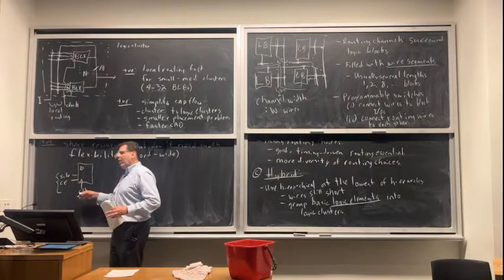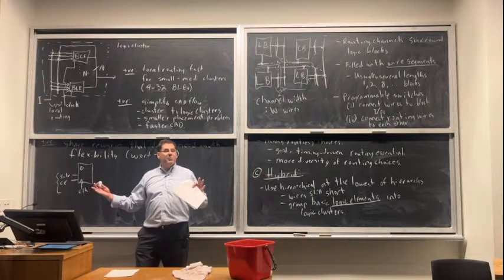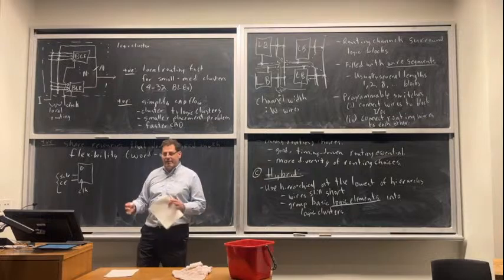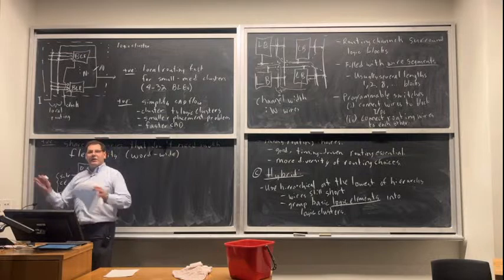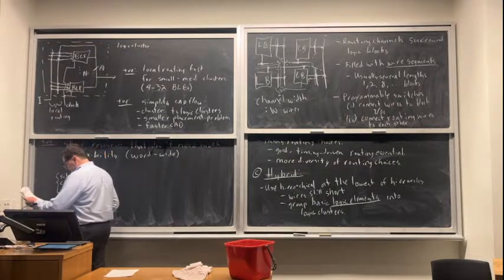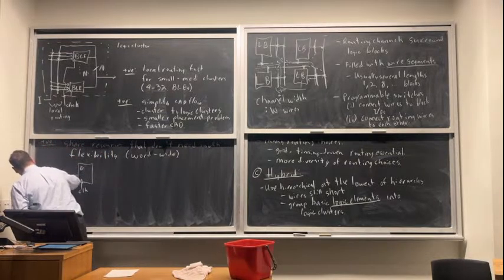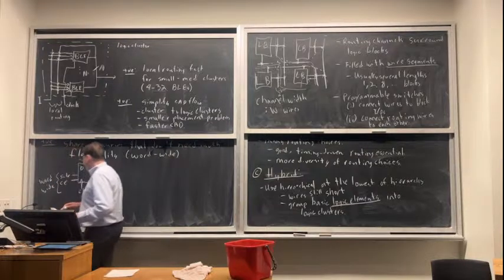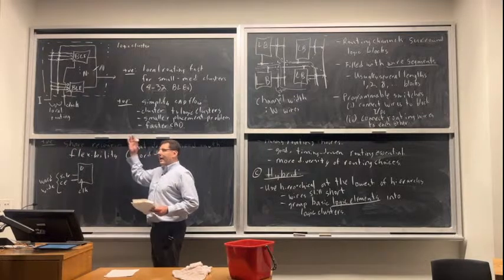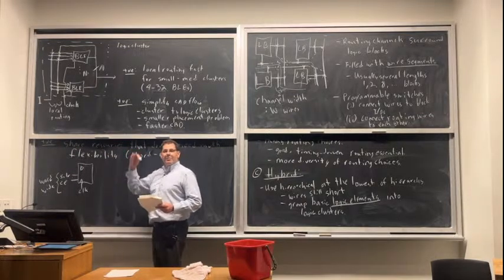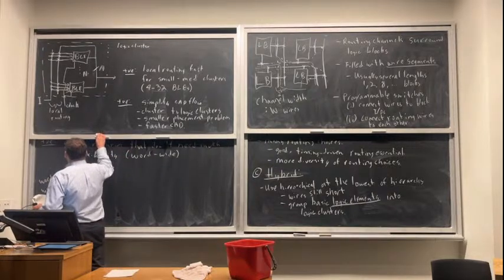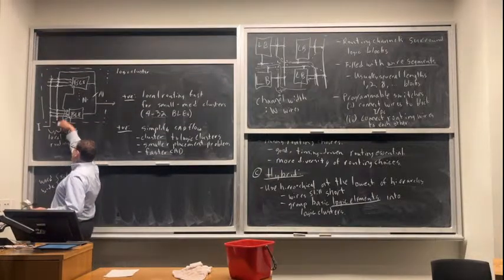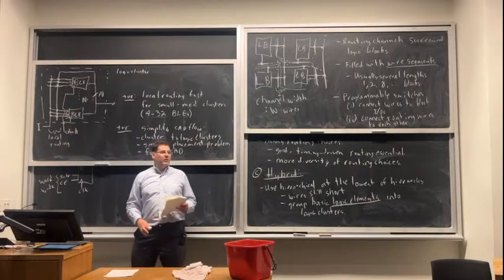And then clock, as I said, is shared even more broadly usually. It's not just like this 16-bit word shares the same clock. It's like all the communicating logic around it shares the same clock. So these are basically these word-wide signals. It's excessive to give separate wiring to each of them, separate programmable switches, etc. So what you can do instead is just force those signals to be broadcast throughout the whole logic cluster, and you save a bunch of area.